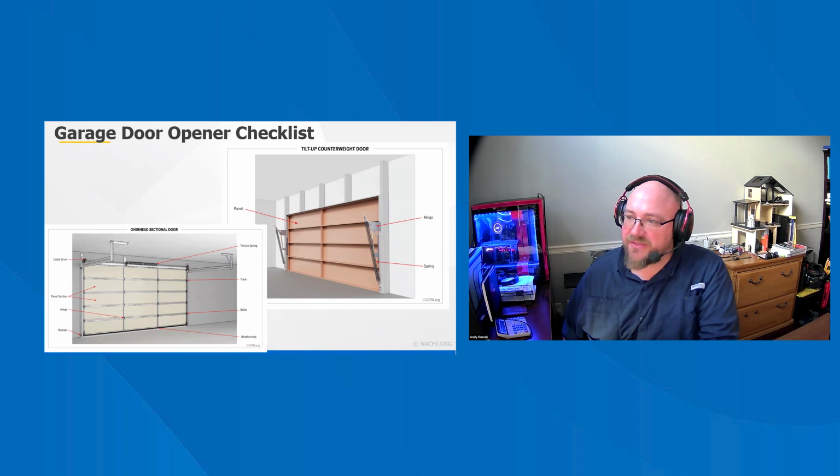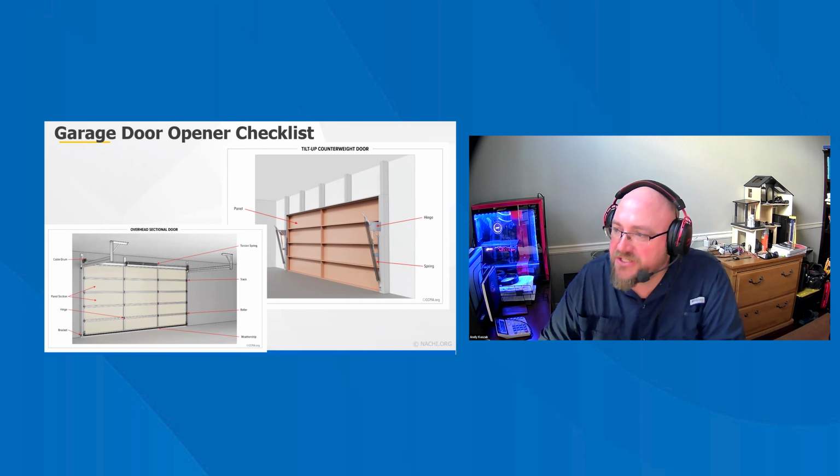Check number one, check the manual release. Begin inside the garage, have the door closed. Check for the manual release handle. The handle should be colored red so it's easily seen. The handle should be easily accessible, no more than 6 feet above the garage floor. The handle should not be in contact with the top of vehicles.